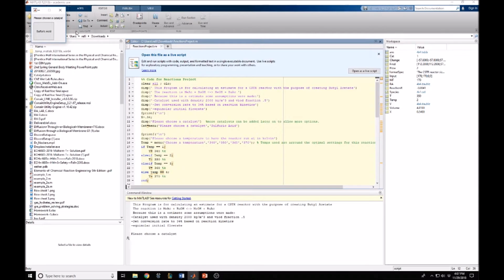Now, in this project, we have several chemicals that have hazards associated with them. Some of those hazards involve: avoid inhalation, ingestion, and contact with the skin or eyes. In order to avoid this, proper protective personal equipment needs to be worn, such as a face shield, a full suit, vapor respirator, and gloves.